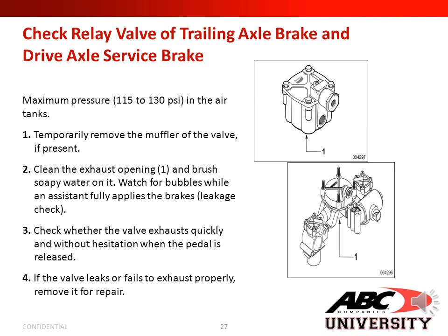Next, we will do an inspection of the check relay valve of the trailing axle brake and the drive axle service brake. Ensure maximum pressure of 115 to 130 psi is in the air tanks. Step 1. Temporarily remove the muffler of the valve if present. Step 2. Clean the exhaust opening, number 1, in the picture shown to the right. The one on top is your check relay valve of the trailing axle. The one on the bottom is your drive axle service brake.